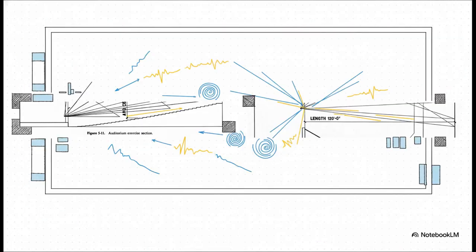So what does 484,000 cubic feet actually look like? Well, in our case, it's a room that's 120 feet long, 96 feet wide, and 42 feet high. And hey, these ratios aren't just pulled out of a hat. They're specifically chosen to avoid something called standing waves, which are basically these really annoying acoustic dead spots or hot spots where certain sounds get trapped and just buzz. So there we have it. The shell of our virtual building is complete.